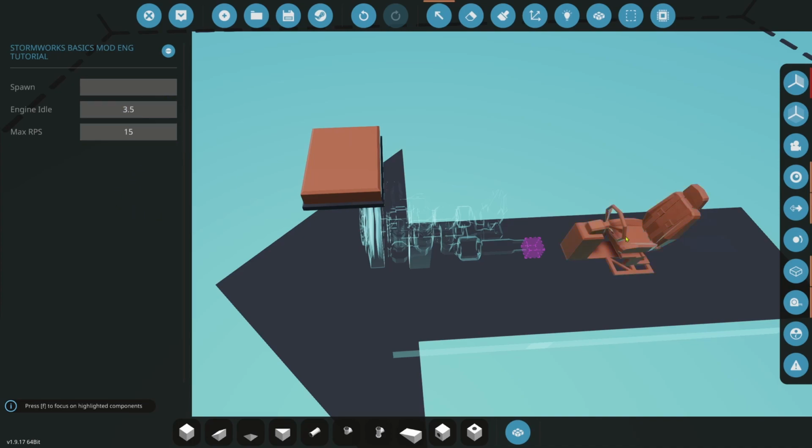So what this allows me to do is, let's say my engine is not going as fast as I like. All I have to do is click on this, press 20. I don't have to go in the microcontroller and search for it. This is going to be helpful for tuning our engine. We can change it right there.